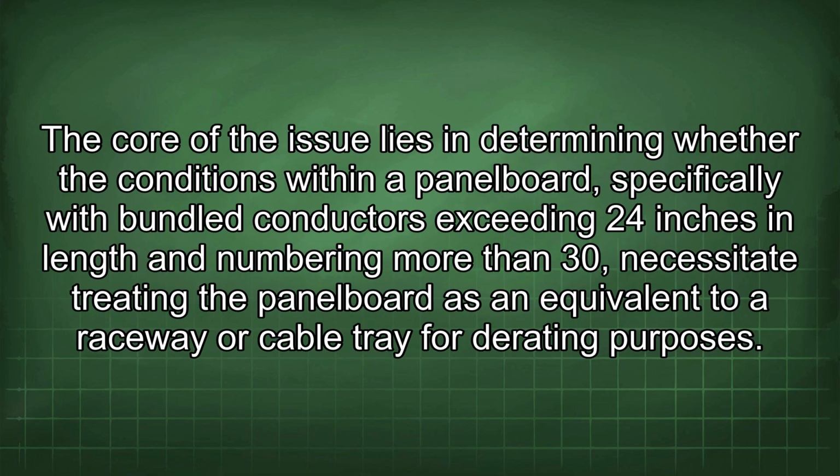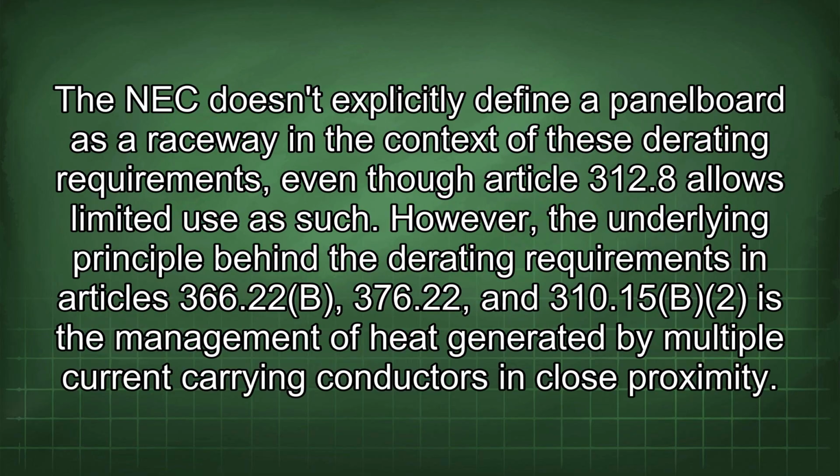The core of the issue lies in determining whether the conditions within a panelboard, specifically with bundled conductors exceeding 24 inches in length and numbering more than 30, necessitate treating the panelboard as an equivalent to a raceway or cable tray for derating purposes. The NEC doesn't explicitly define a panelboard as a raceway in the context of these derating requirements, even though Article 312.8 allows limited use as such.